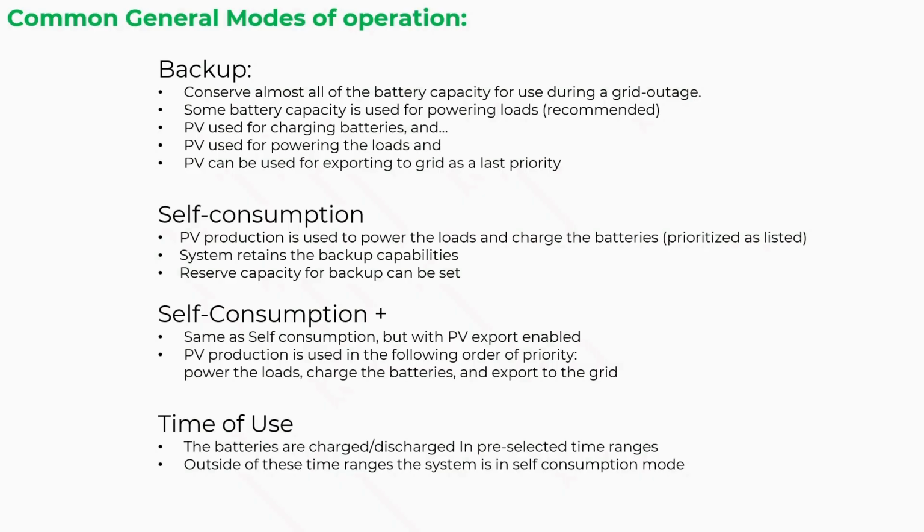The last but not least is time of use. In this mode of operation, the batteries are charged and discharged in pre-selected time ranges to accommodate for changing electricity rates throughout the day. Outside of the selected time ranges, the system is in self-consumption mode.